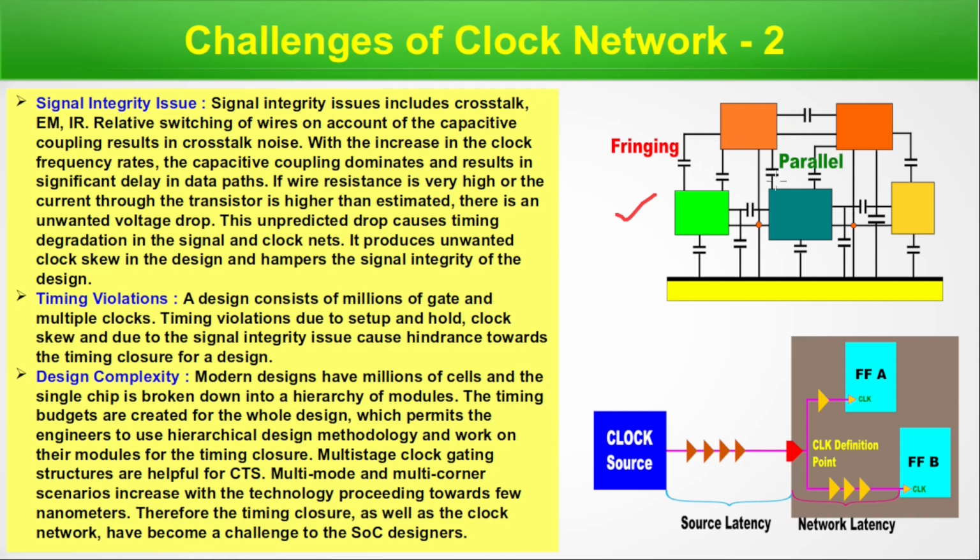So it's working as a capacitor. That thing is crosstalk. The relative switching of wires on account of capacitive coupling results in crosstalk noise. With increase in the clock frequency rates, the capacitive coupling dominates and results in significant delay in data paths.